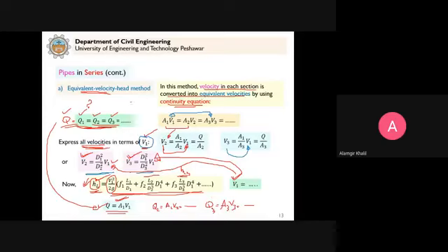In this, what we essentially did is that we expressed all the velocities in terms of one velocity, which is, let's say, V1 here. You can also express all the velocities in terms of V2 or in terms of V3. Still you will get the same result. Clear? So this is how we will solve the problem when the head loss is given to us and the discharge is what we have to calculate. You can calculate just this and these two. This will serve as a check.